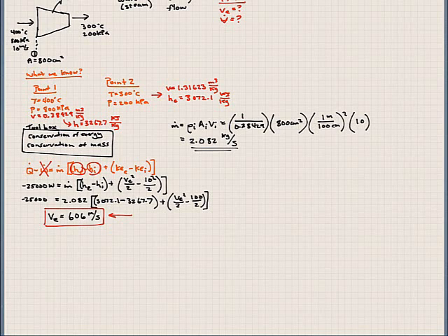Let's now find our volumetric flow rate. So knowing that we have conservation of mass, there's nothing else coming in, it's a steady flow system, we can say the sum of the mass flow rates coming in equals the sum of the mass flow rates coming out. We only have one inlet, one exit, so mass flow rate in equals mass flow rate out.